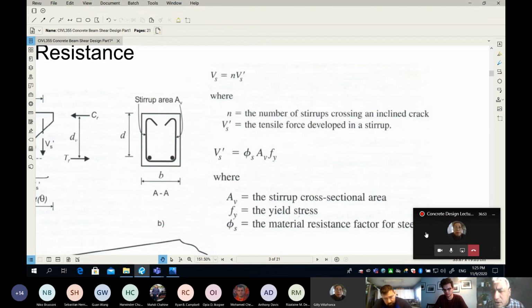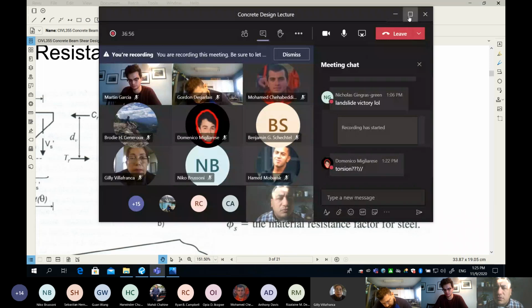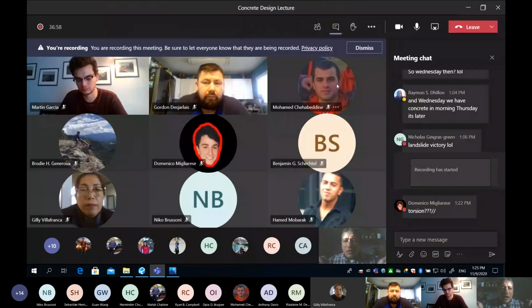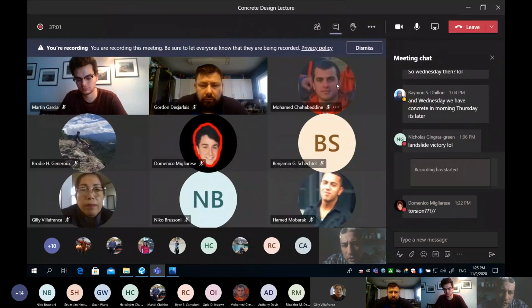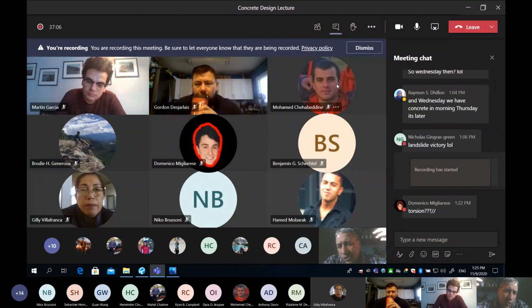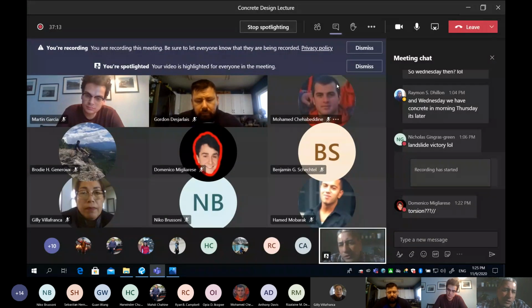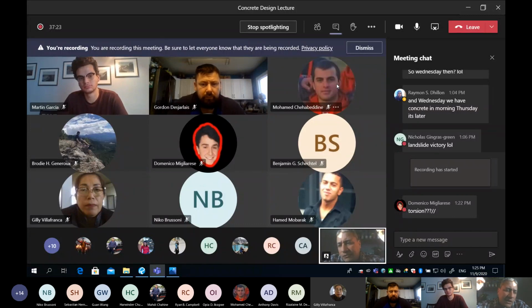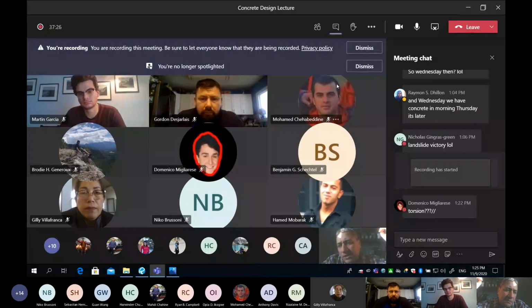And guys, this will make our life very easy. If I give you a single bar, like in strength of materials first year, that has a known cross section, can you anticipate what force will fail the member if I tell you that Fy is 400? What's the meaning of 400? It means every square millimeter can take only 400 Newton per millimeter square. All you have to do is multiply by the area. If you multiply the area by the stress, you get the force that will tear your section.